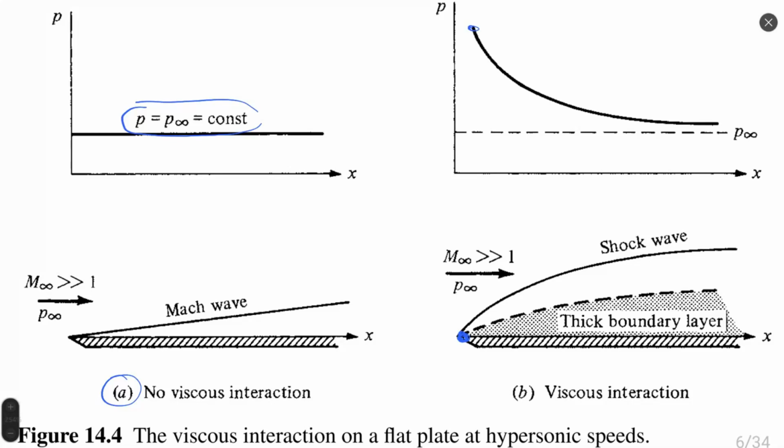This point is small, but this rise of pressure will always exist, because of the presence of a boundary layer with some thickness. The boundary layer is the reason why the elevation of pressure at the leading edge happens. And then when the boundary layer becomes more or less stabilized, it becomes more constant.